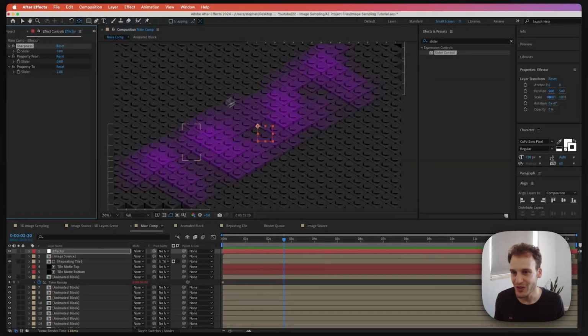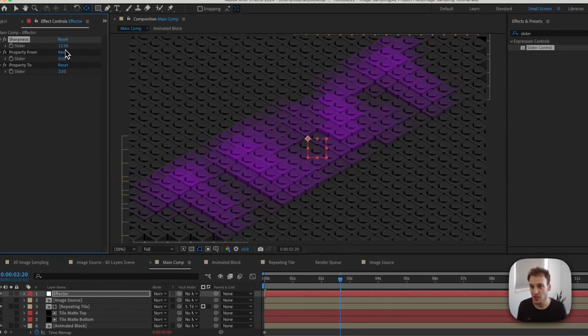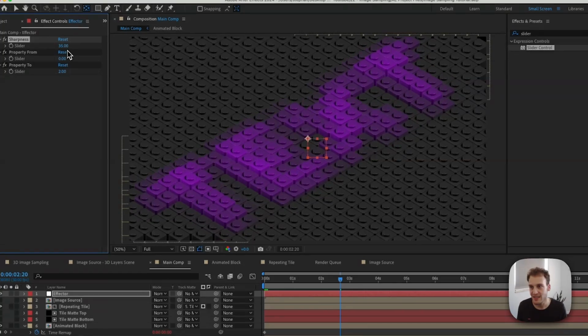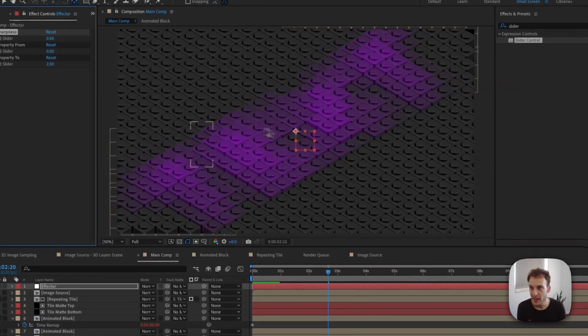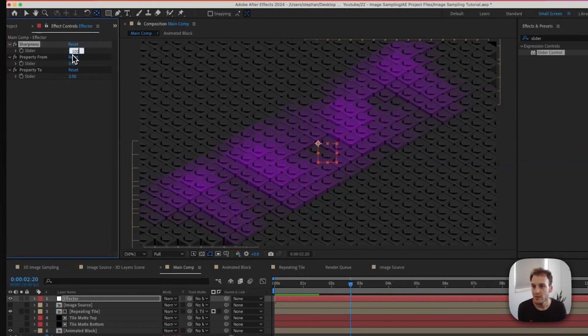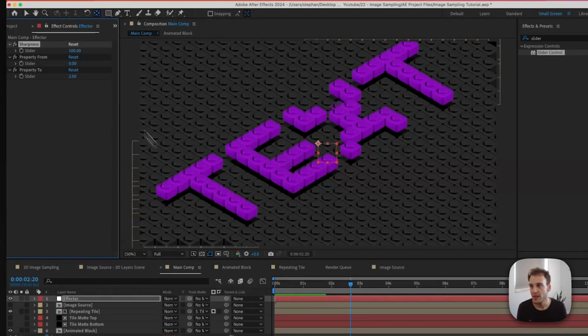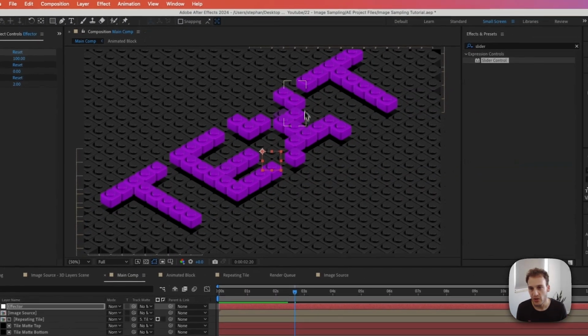Of course, right now we are not completely seeing this. That's because of the sharpness. Right now the sharpness is set to 0. If we increase the sharpness slightly, we can start seeing this being more visible. If it is set to 0, it is kind of blurry. If the sharpness is set to 100, it is 100% visible and takes the sharpness of the text 100%.